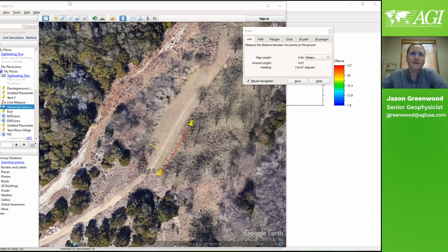But that logging mode menu was added for submarine groundwater discharge, which would be one tidal cycle, which may be 5, 8, 12 hours. So you would leave a marine cable out, which is much less likely to be damaged, like on a quiet beach setting with sandbags over it. And that's what that functionality was added for. So there is built-in time lapse on the SuperSting itself.